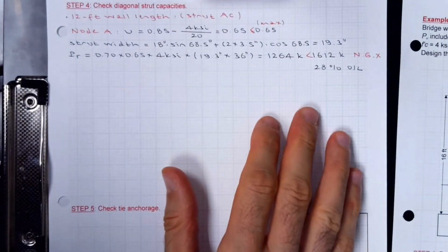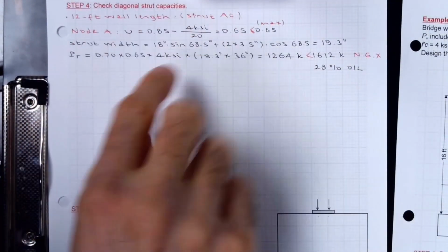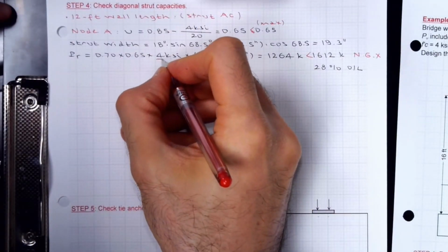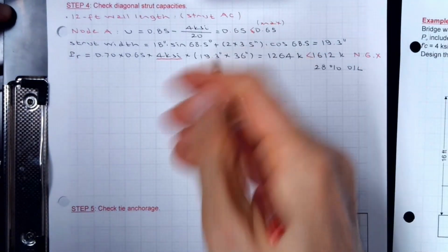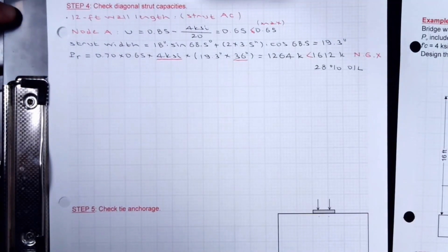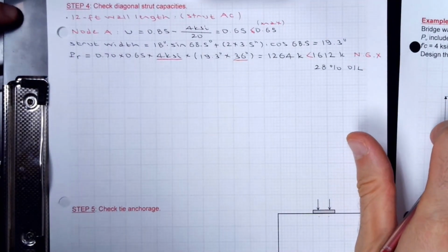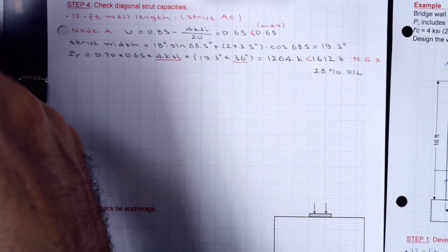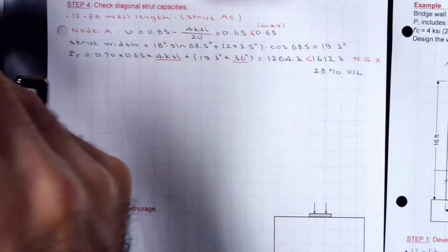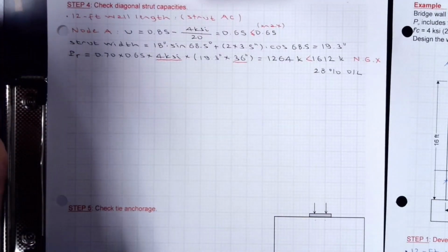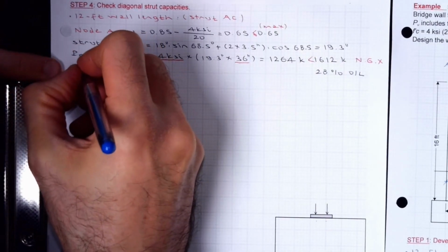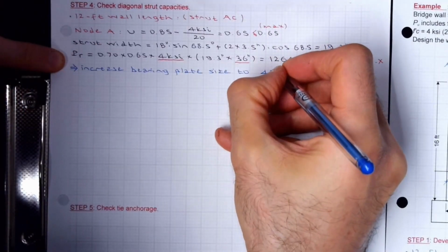So definitely there are multiple solutions for this. You see the equation, you see what's input into the equation. You might increase concrete strength. That would enhance your design overall. You might increase the thickness of the section. That's another one. If you don't want to change these, bearing plate would be the one. My solution would be to increase bearing plate size. It was too tight to begin with. Remember, we had to use the confinement modification factor. So I think for this situation, the first solution attempt should be to increase size to 42 inches.